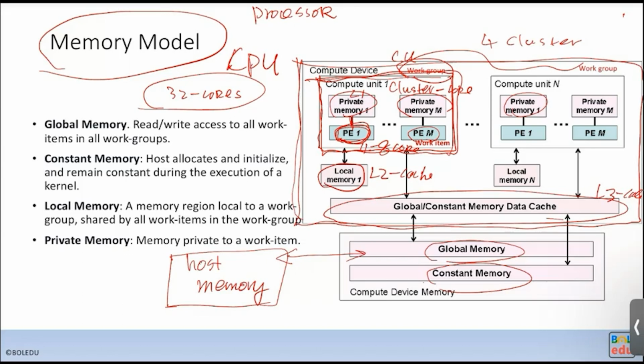In an FPGA, you partition the data and then you have to explicitly move data around, and your program code has to make sure that if you modify a part of the data here, and you want another kernel function or PE to process the same data, you explicitly transfer the data to its private memory.